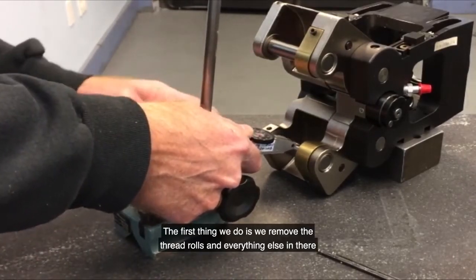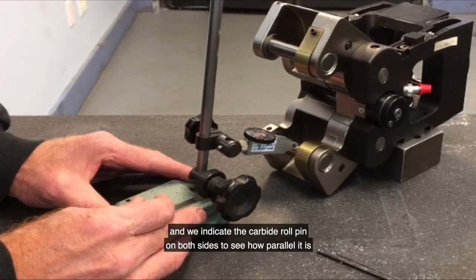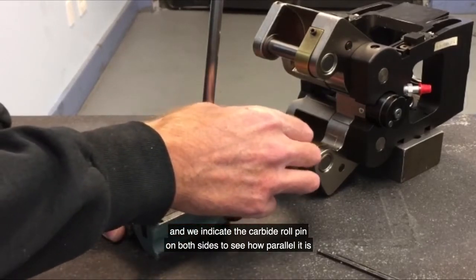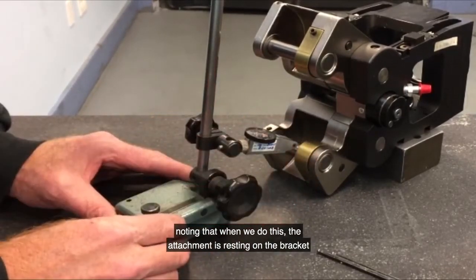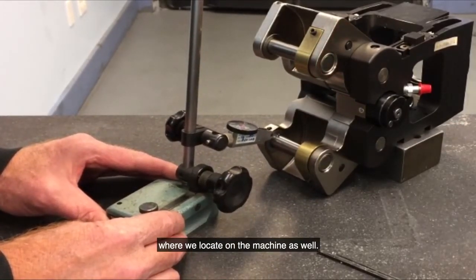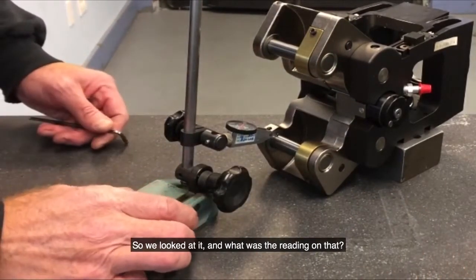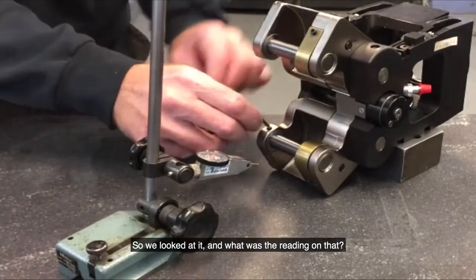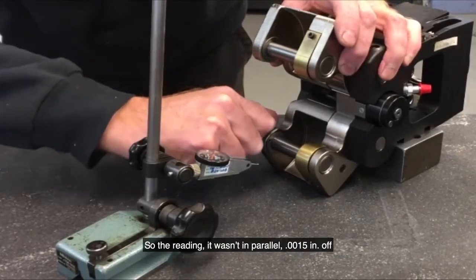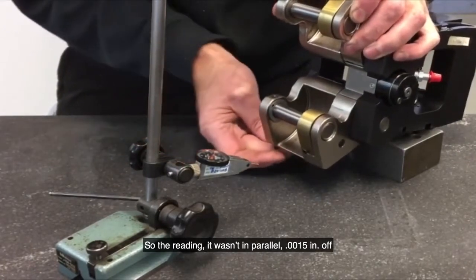The first thing we do is remove the thread rolls and everything else from there, and we indicate the carbide roll pin on both sides to see how parallel it is. Noting that when we do this, the attachment is resting on the bracket where we located the machine as well. So we looked at it, and what was the reading on that? It was off by a thou and a half. So it wasn't parallel, a thou and a half off.